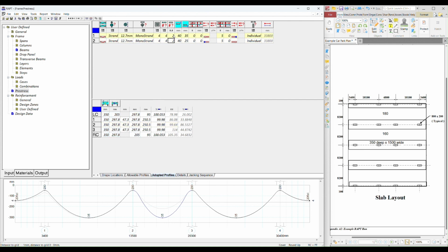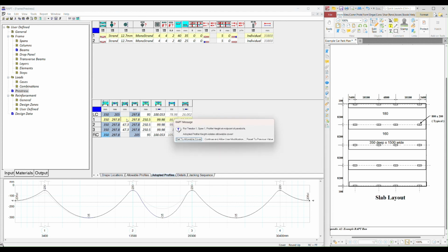We had 4 before, so we now have 2 and 2, both equal and opposite, if you like. Just got to make sure with this one that we've just added that we ensure that the drapes are the same. So let's change that. Our axis distance on the bottom was 45 millimeters from memory.